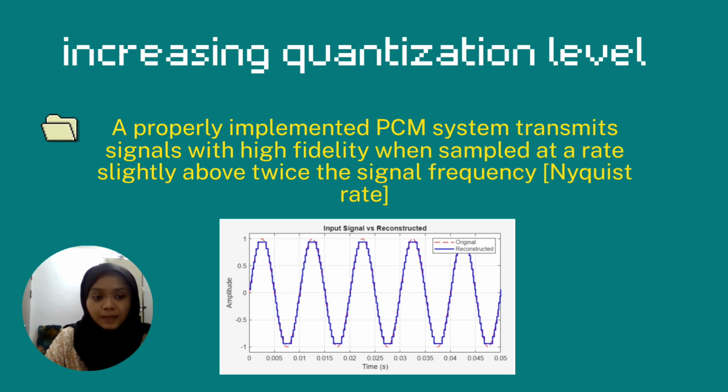In our simulation, we noticed a stair-stepping effect in certain parts of the signal, especially when the waveform changes smoothly. This is the result of the quantization noise caused by limited bit resolution. By using more bits, we can reduce this distortion and achieve a signal that is even closer to the original.